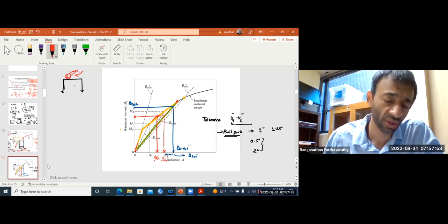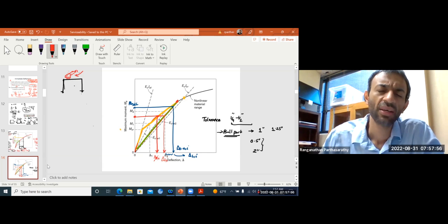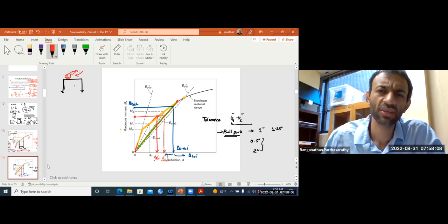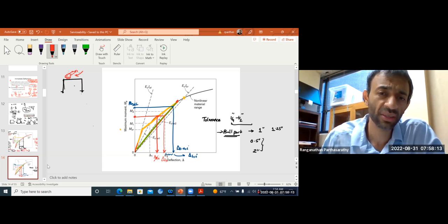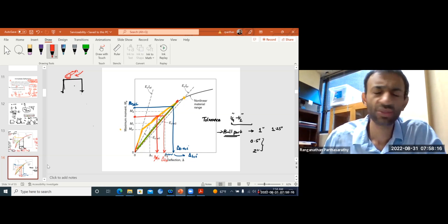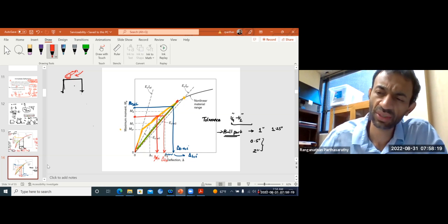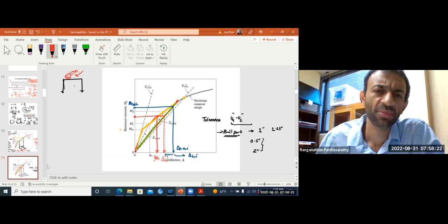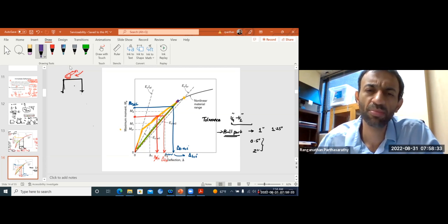Okay. Now there is another case where, at some point of time during the construction of the structure, and this is also quite common for many structures, especially where you are bringing in very heavy construction equipment, let's say precast bridges, reinforced concrete pipes, box culverts, and so on, whatever loads were coming during the construction are much more than your live loads. Okay, so your construction loading is the most critical. That means before your live load is being applied, at some point it has already reached a very high level of cracking. Let's say this purple point.